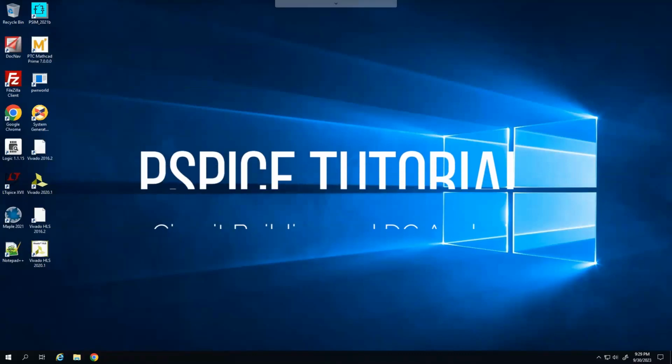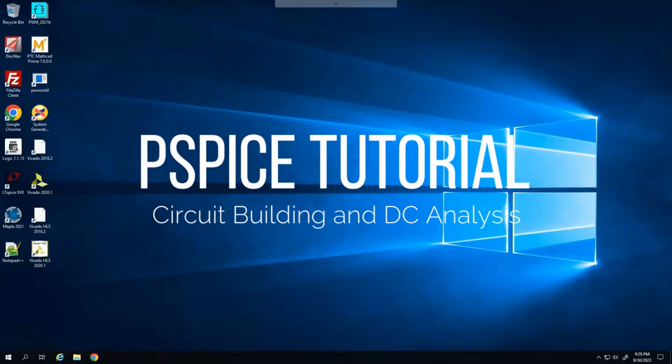Hello, and welcome to a tutorial on how to use PSpice. PSpice is a simulation tool where we can build circuits and find important measurements. In this tutorial, I will discuss how to navigate to PSpice, a couple important options to toggle, how to place components and build circuits, and finally how to perform DC analysis.